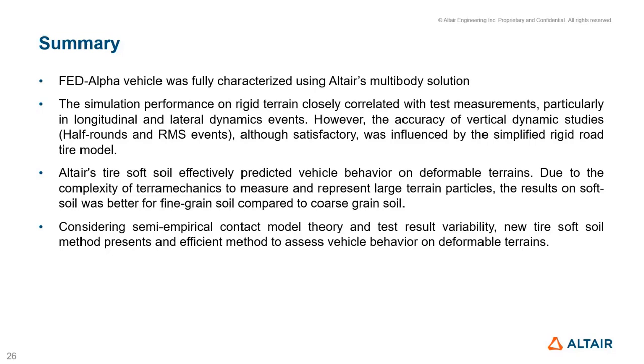And this is pretty much aligned with the theory of the soft soil, what the Bekker and Wong equations provide, right? So whenever you have coarse grain, the physics of the thermomechanics is a bit complex, and it would be better represented using EDEM, for example, right? To represent with a discrete element method. But for soil types such as fine grain sand or mud, these would be very well represented.